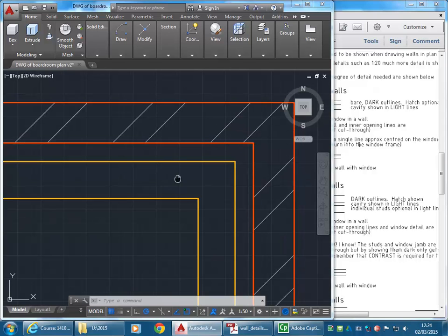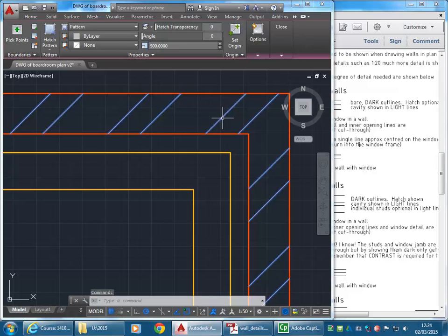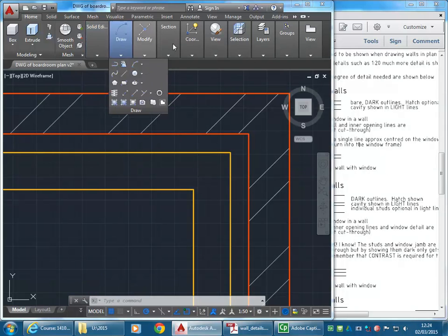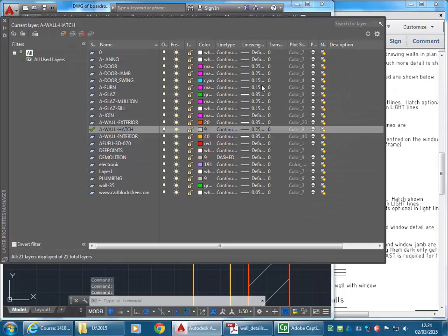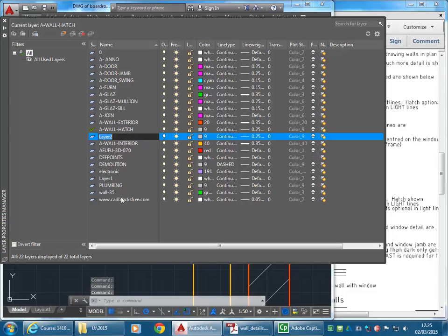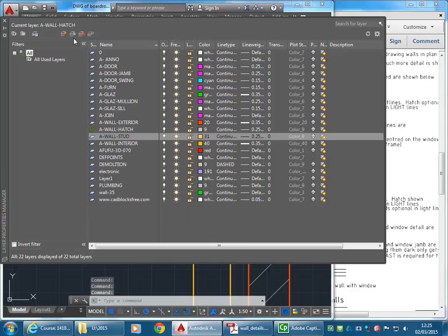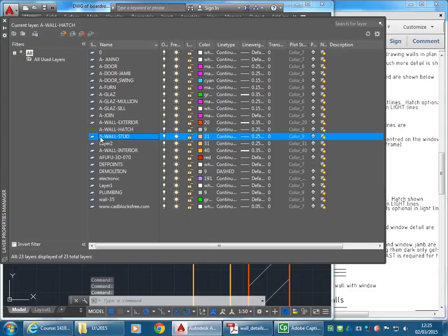for brickwork. And then if we're going to do this for 1 to 50, you draw in your studs. So again, I'll make a layer for those so that I can turn them off. You could do it on your interior layer, but I'll make a new one and call it a wall stud, or studs, but a wall stud will do. And I'll just make it yet another colour. Oops, sorry, I meant to make that current layer. Just get rid of that.